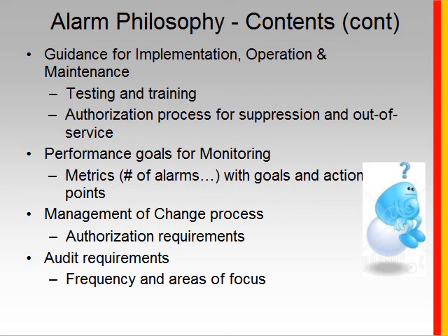What are the targets for how you want the alarm system to perform? And by this I mean the number of alarms that are presented to the operator, the number of nuisance alarms, and all that kind of good stuff. Because we're going to show later that in the life cycle we're going to measure those things. We're going to benchmark against what we said we wanted to achieve.